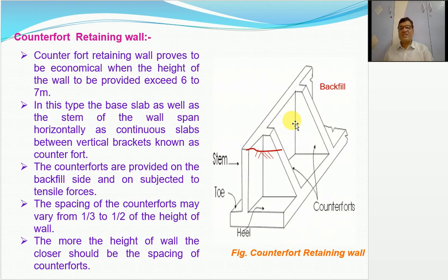Okay, it's obvious. Now, by virtue of the position of these counterforts, these are subjected to tensile forces. See, now along on this stem wall, the force is acting away from the backfill, that means towards this side, and on this base slab, because of heel slab, the force is acting towards the bottom side.